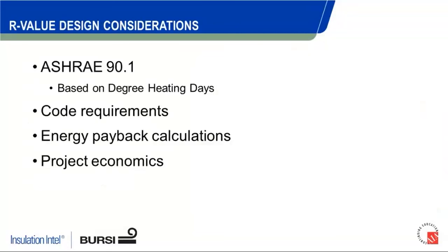So how do you know how much insulation you need in a project? That goes back to your building code, or whatever code has been adopted in your area. That's either going to be an ASHRAE 90.1 or the IECC codes. Different years for different locations, so make sure you understand what code you're working under and what those minimum requirements are.